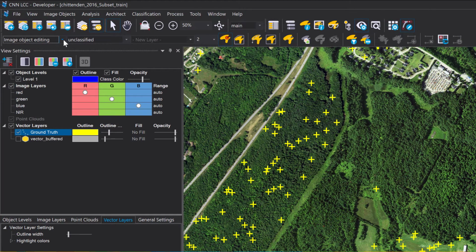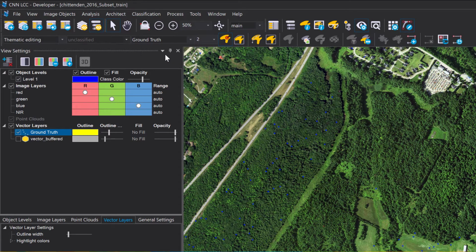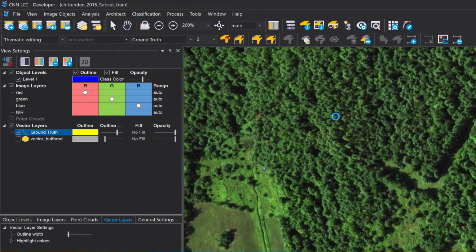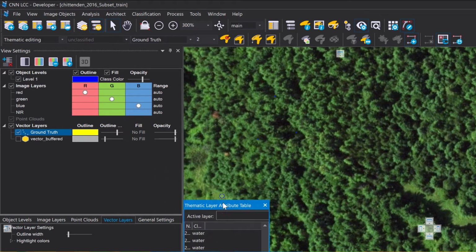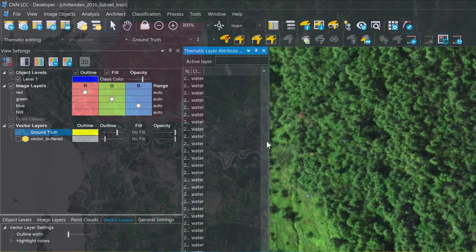So what we recommend is, for labeling, you can use the manual editing tools in eCognition to draw points, lines, or polygons that represent the classes you want to create samples for. We also recommend that you do not evade difficult, unclear, blurry border regions of the classes that you want to classify, for example, forest. Otherwise, your network will only learn the easy targets, and that will give you disappointing results. We also recommend that you invest significant time in labeling initially, even before the first try, because the samples are highly important for deep learning.